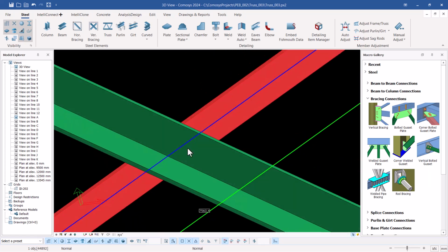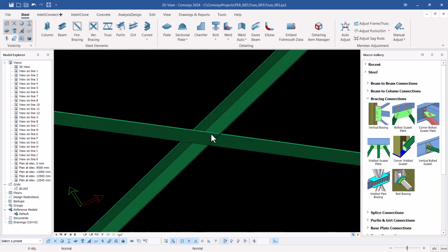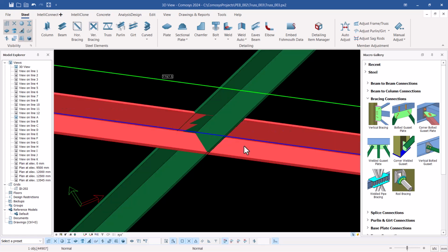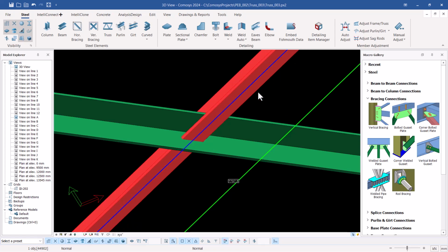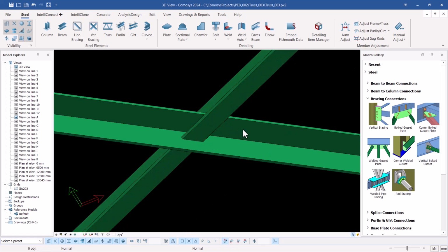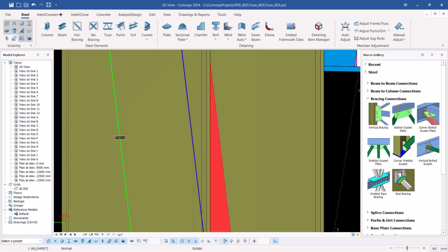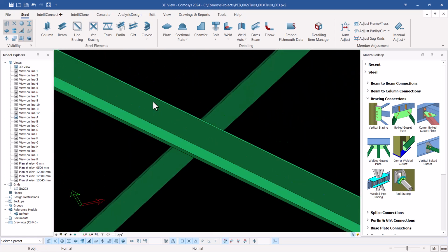So I'll be able to just place a bolt and connect the other end. So if I zoom out, I'll do the same thing to this one also. I'll be able to just select on this, then press Ctrl Q and turn that back to the other end, and press Ctrl Q here once again. Then press Ctrl E and take that behind to create a space. Then press Ctrl E once again, and this will come this way. So if I put a bolt here, I'll be able to create a nice connection instead of placing a gusset plate in between. So we just bolt them together.